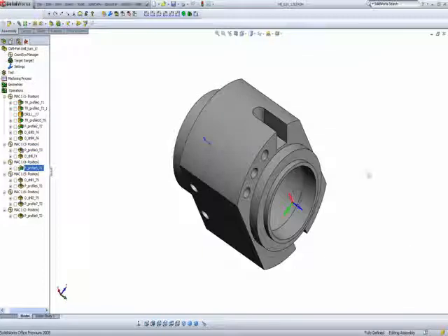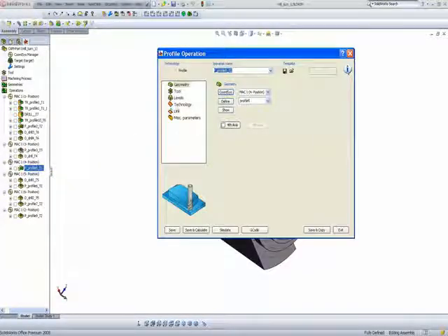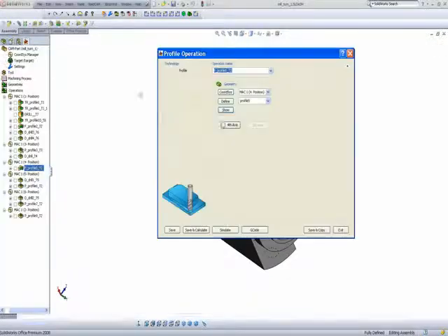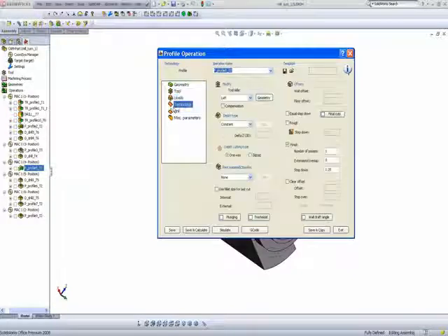Now in my next milling operation, I'm just moving along, and I'll be cutting out this area. So for that I have my Mach 1 4th position, and again just a simple profile operation to mill out that area. As you can see within the operation itself, again my geometry, my tool, my levels, technology, everything that is needed to complete this part.